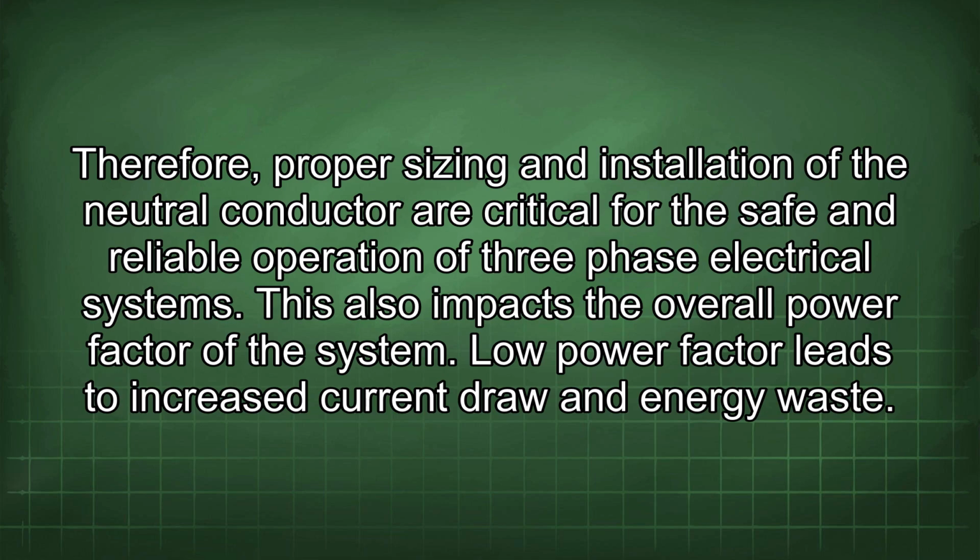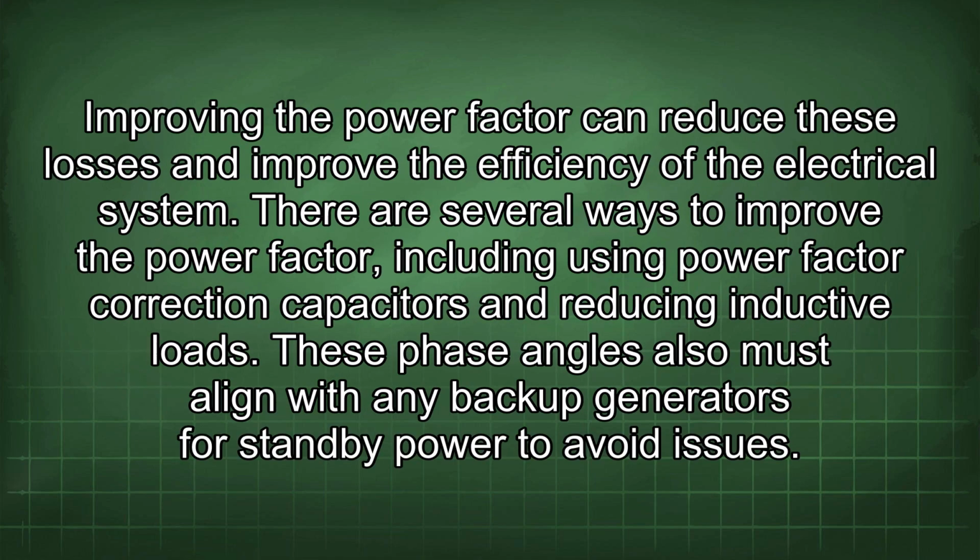Low power factor leads to increased current draw and energy waste. Improving the power factor can reduce these losses and improve the efficiency of the electrical system. There are several ways to improve the power factor, including using power factor correction capacitors and reducing inductive loads.